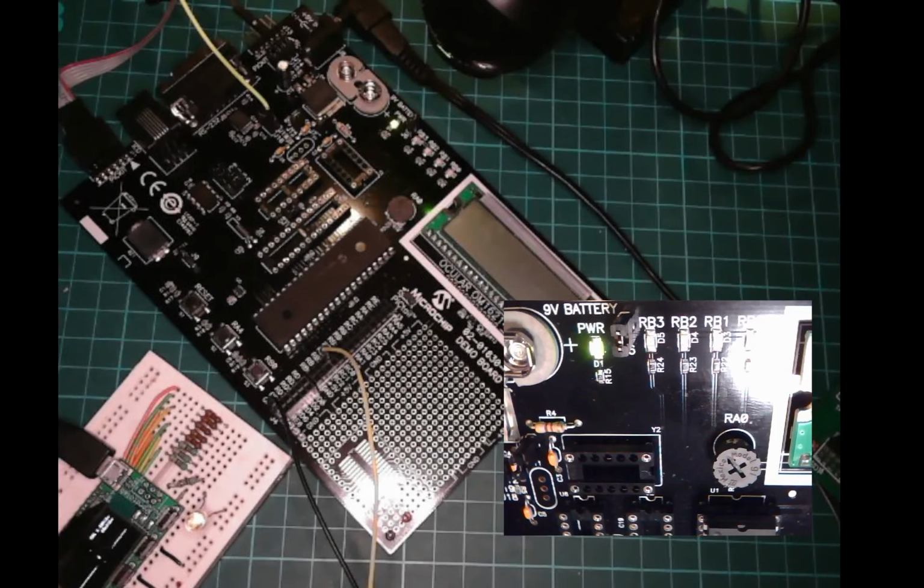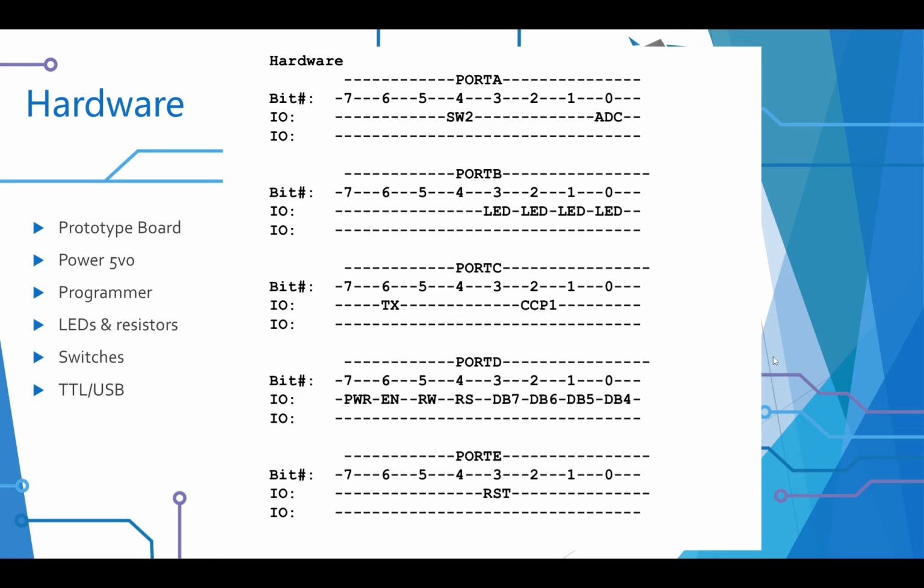What we're going to see on my PC is some results. I've actually got it hooked up at the moment to RB3, but shortly I'll have to go to CCP1 because that's what we're going to be using. That is where the pulse width modulation signal comes out on these boards. You can't change it. It's fixed on that port. Go to the data sheet and check it out. On some chips, you can move it to one other alternate.